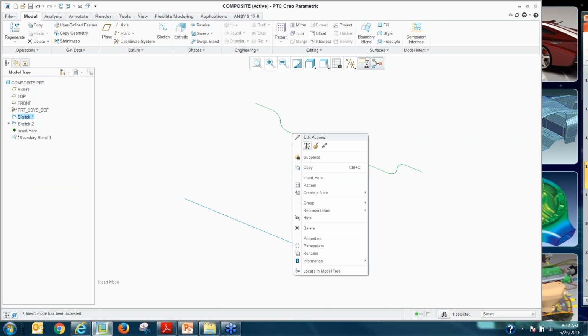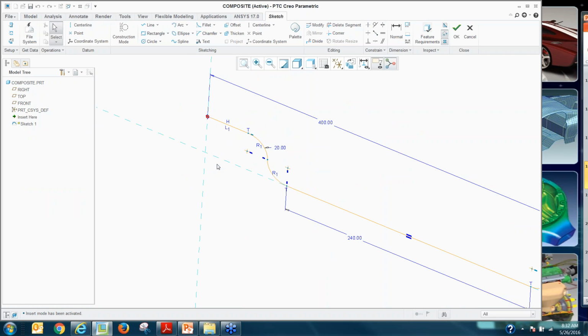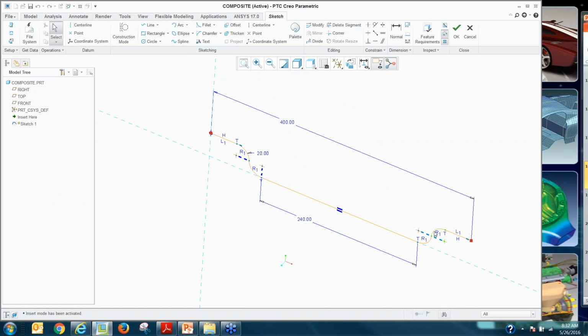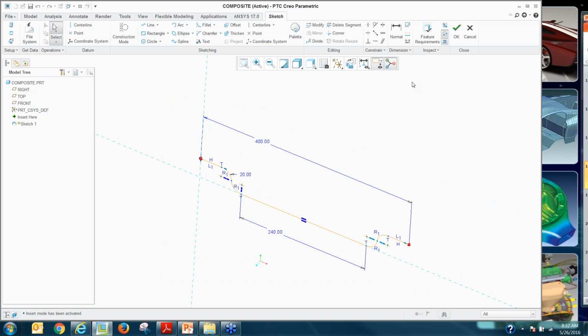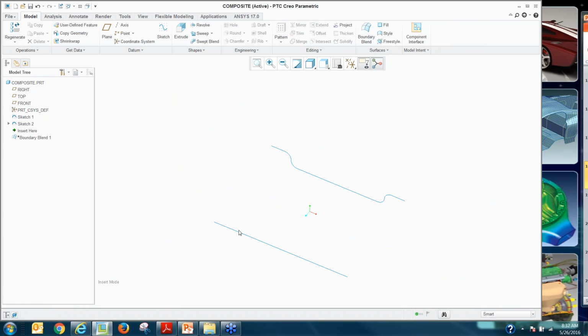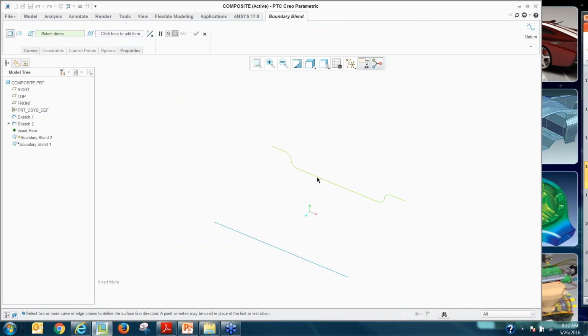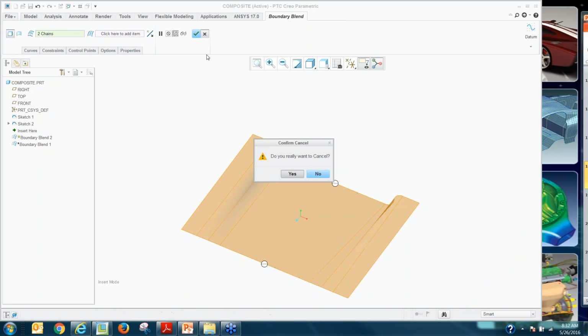So this curve, if you think about it, the way it was done is using line curves. You can see how it's made of these multiple entities, and now you know why the patches are there. There was a tangency point, which makes sense why it created a patch through that, right? It's trying to blend that to a straight line, right? And this may have additional points, and that's how it got it through. Now, currently when I do a boundary blend and say, okay, this guy blends to this guy, you see how it creates those natural vertices that convert into patch lines.